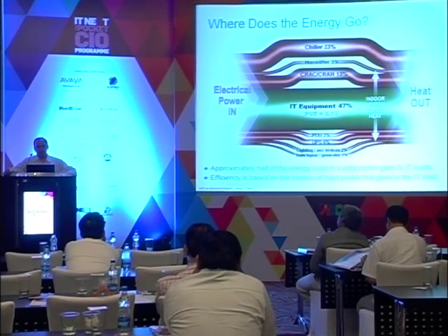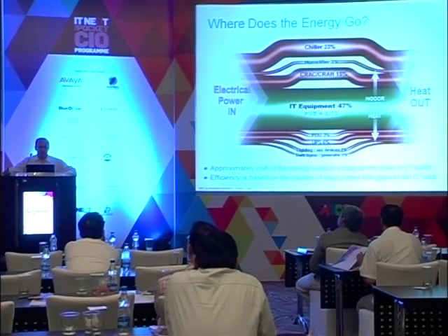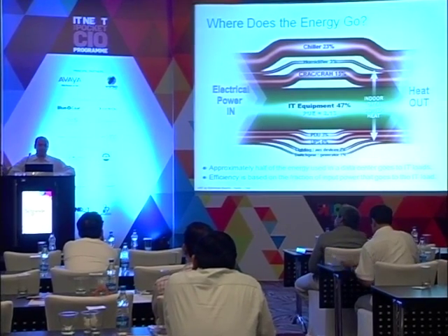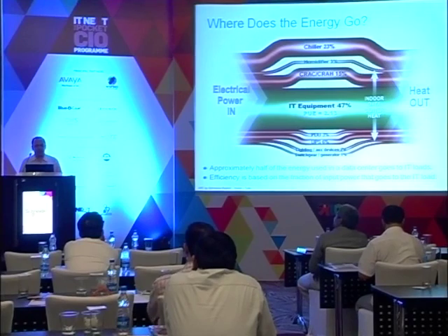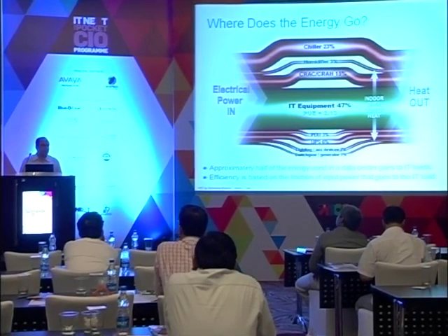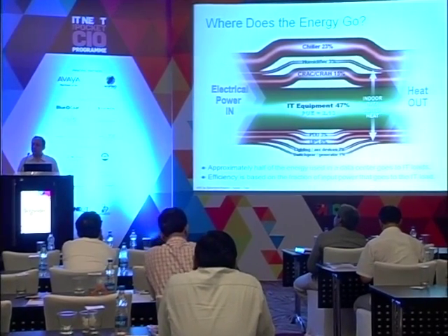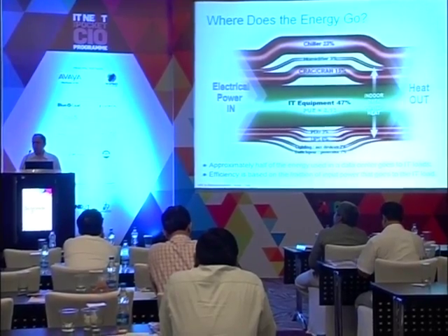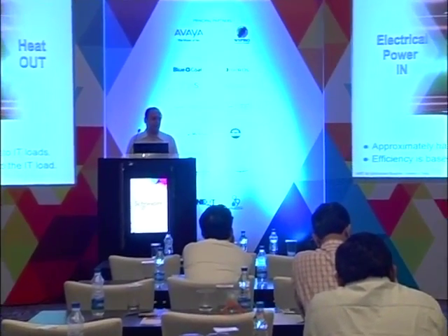So looking at the nature of its definition, a PUE can go from best case of 1, wherein nothing is consumed other than the IT equipment, to going as high as infinity, right? So that's the range that we can talk about. So just because we have a PUE of 2 and another with a PUE of 3, we definitely know that the PUE of 3 is worse as compared to the PUE of 2. We also have acknowledged globally that PUEs typically range between 2 to 2.5 globally, right? And this is impacted in a big way by the outside climate.